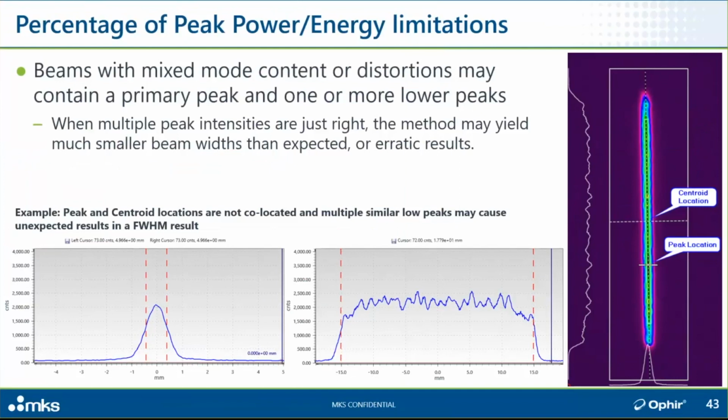Not every beam width measurement and beam width method can be used in all cases. And sometimes we see users that are very stuck on using a particular method, even though the laser that they're using and the rest of the signal, their application, isn't going to really support that measurement well. And there are alternate methods which will have good correlation to what they're trying to do, but they're stuck on using this one method. We would recommend against doing that. There's many methods, and you should use their strengths and weaknesses appropriately.